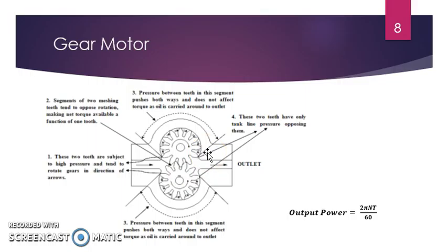The side load on the motor bearing is quite high because all the hydraulic pressure is on one side. Here the oil enters the inside of the motor, then it is trapped between the tooth and casing, then drawn into the outlet port. The pressure of the oil rotates the motor.